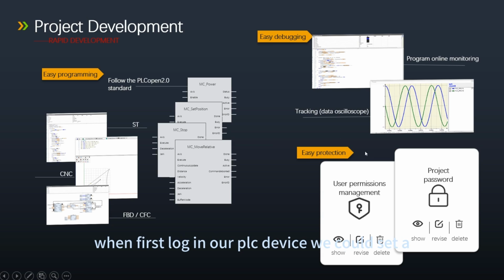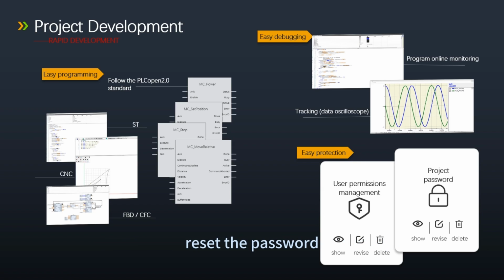When first logging in to our PLC device, we can set a password for it to protect the hardware, and also we can set a password for the project to protect it. But for these PLC passwords, please remember them, because if you forget them, you need to send it back to the factory to reset the passwords. It will be troublesome.